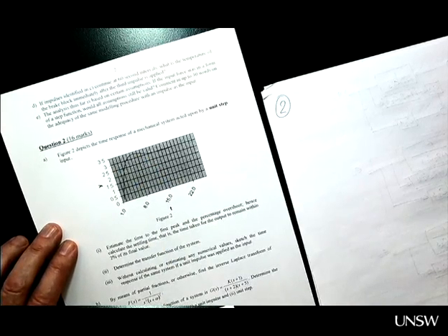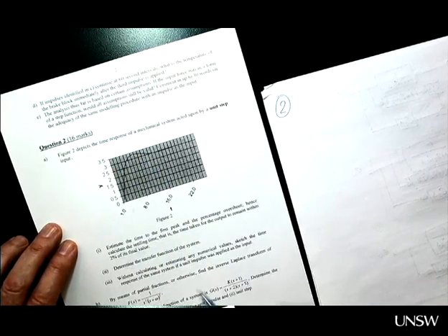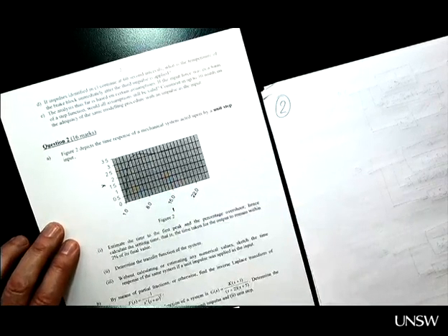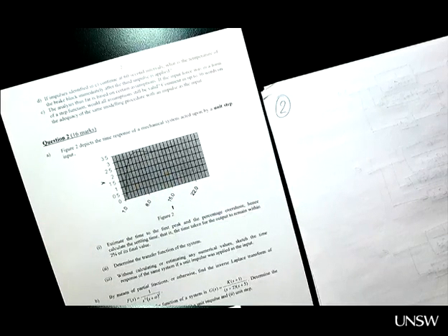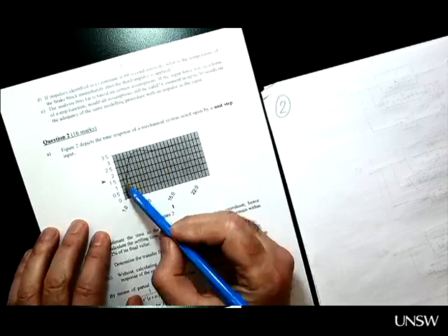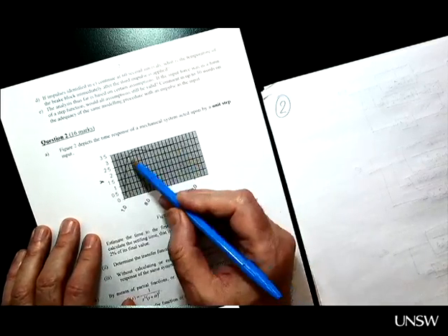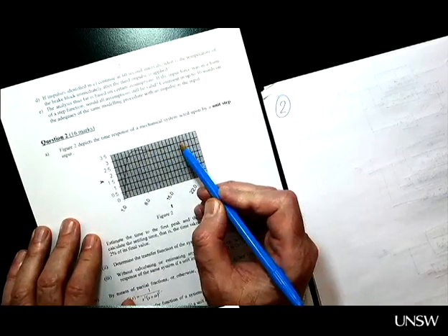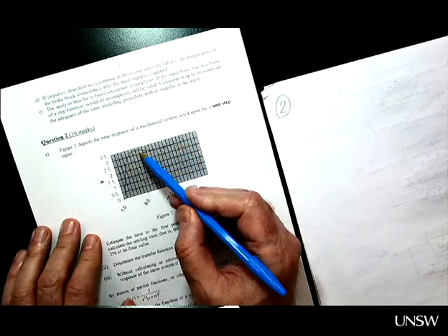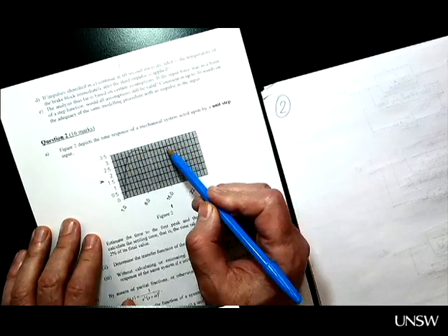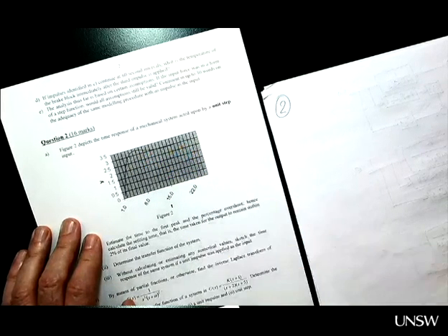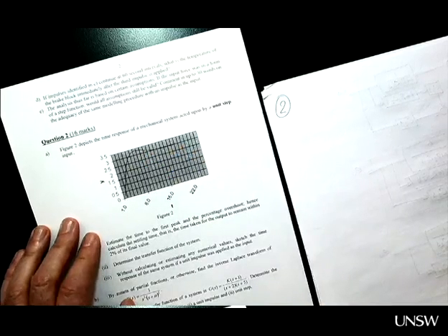And if you look into the graph, therefore my initial question, you need to have an idea how the graph looks like when you have an overdamped or underdamped or critically damped or even undamped system. And this is an example of an underdamped system. So you have some oscillations that disappear after a while. Therefore, you have an overshoot, you have the first peak, the second peak is really small, and the third one is invisible in this graph. So it is an underdamped system. So transfer function.